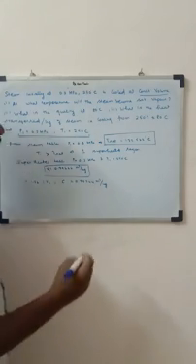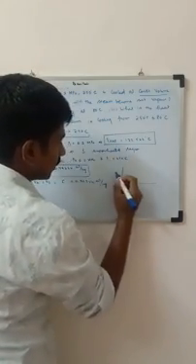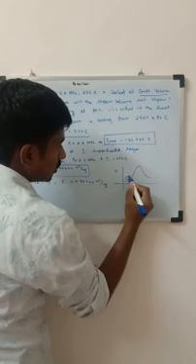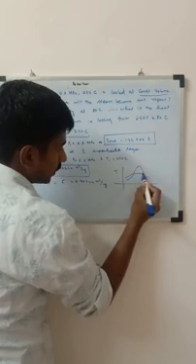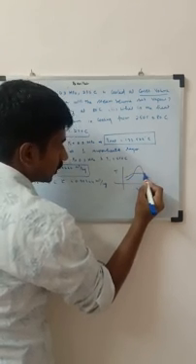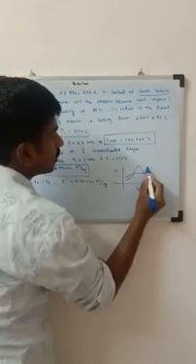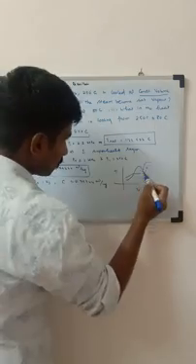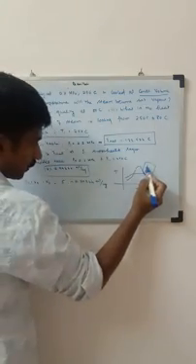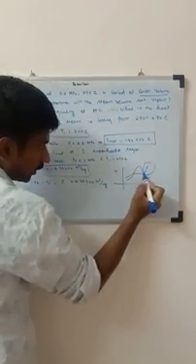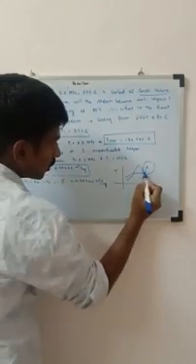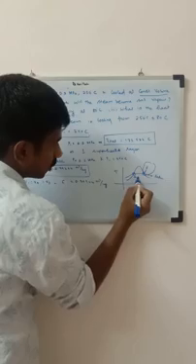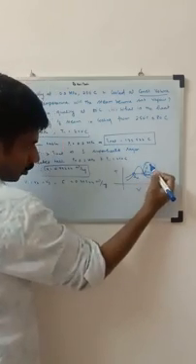What is saturated vapor? When we draw this, let's say a T-V diagram, it's going to look like this. We increase the temperature and the volume, and then it remains constant till all the water is changed into steam, and then the temperature further increases. So we start at this point, in the superheated region. Then I start cooling it. When it reaches this point, it will start changing its phase. So this is the point of saturated vapor, and this is the point of saturated liquid. Now I am in this region, and I am going to cool my steam.